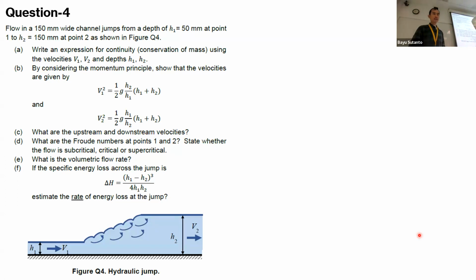This is like in designing a dam, when you release water at high velocity and then suddenly discharge to atmospheric, so it can expand, making a hydraulic jump, expanding the flow.